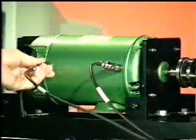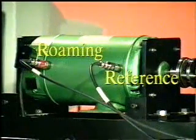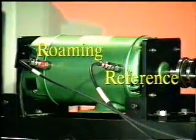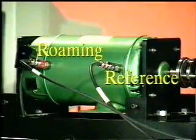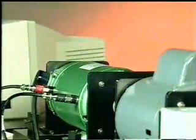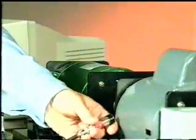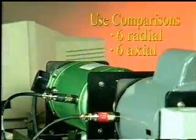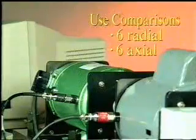Now select one sensor as the reference and the other as the roaming sensor. In some multi-channel analyzers, the X channel must be the reference. In systems using A and B channel references, the A channel typically is the reference channel. Then make the measurements, storing the data for later retrieval and analysis. With the multi-channel instrumentation, the same 6 radial and 6 axial comparisons should be made as with a single-channel analyzer.